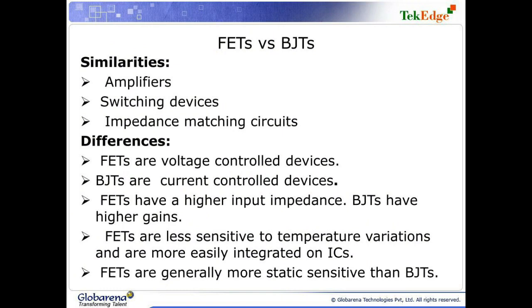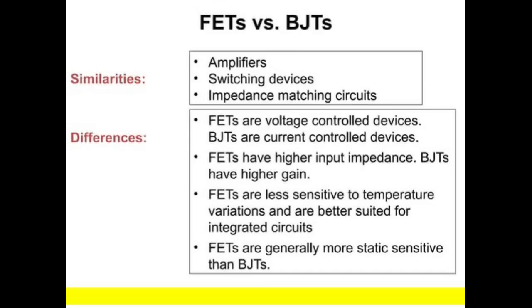The first is thermal stability. Silicon can operate at higher temperatures up to 150 degrees Celsius without significant leakage current, whereas germanium starts to fail above 75 degrees Celsius due to its smaller band gap, which leads to increased thermal generation of carriers.